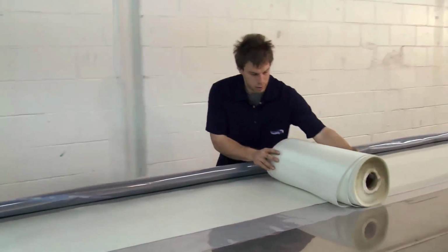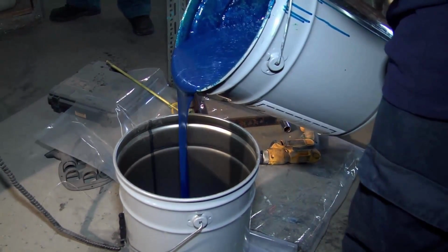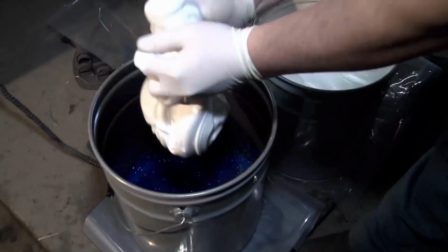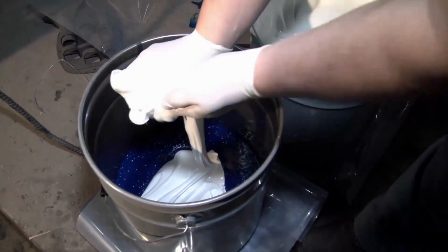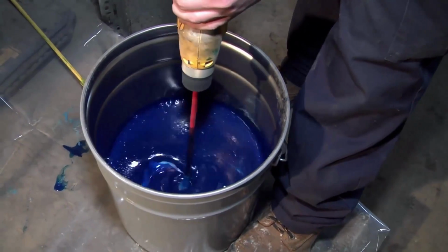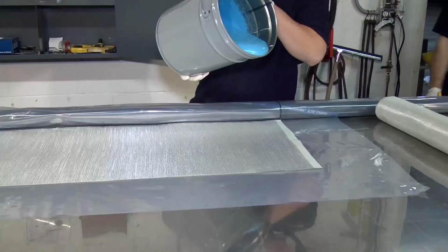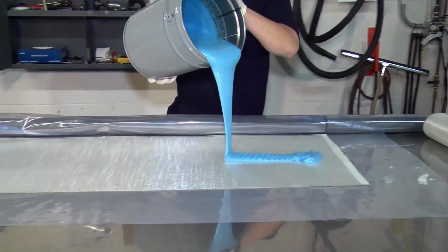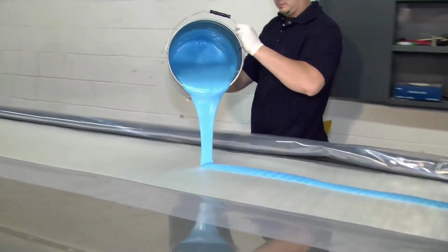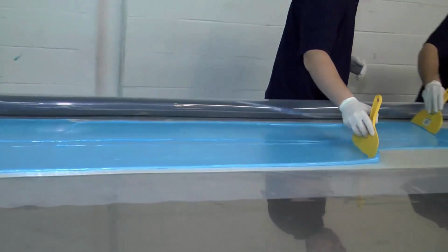So layer by layer, we're going to lay this down and then wet out. This means we put the epoxy over the fiberglass. Every single fiber has to be covered. The amount of resin that's going to be put on this fiberglass is precisely calculated, and we can find that information in the installation manual. So for every single pipe size, every length, you're going to know exactly how much epoxy to weigh, and you have to spread the whole thing on the fiberglass.